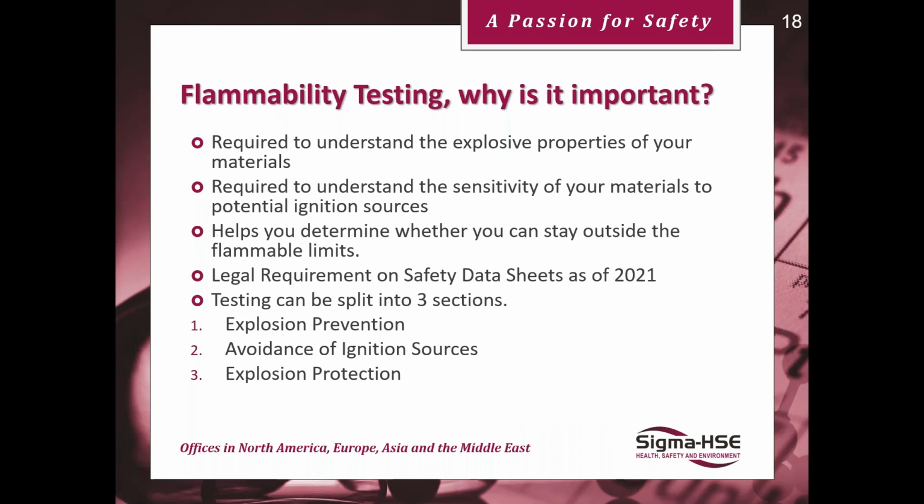The data can also be used to see how far away in normal circumstances you are from a material being able to be ignited when you select explosion prevention, or you select explosion protection, where you need to know the violence of the explosion. Helps you to determine whether you can stay outside the flammable limits. As I said, with dusts, you've only got a lower limit, no upper limit.